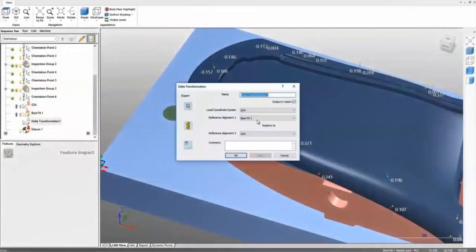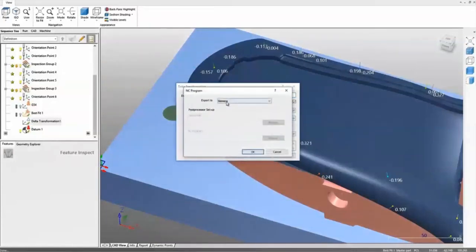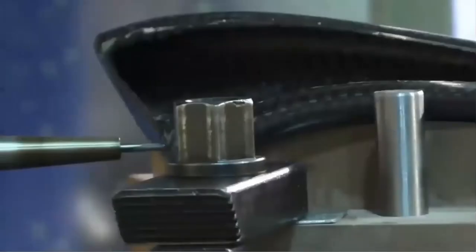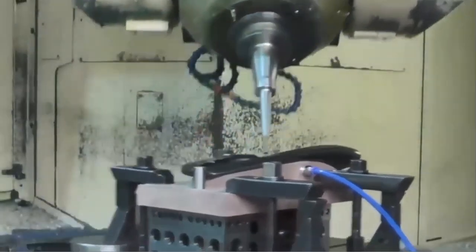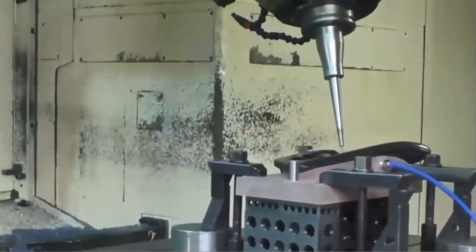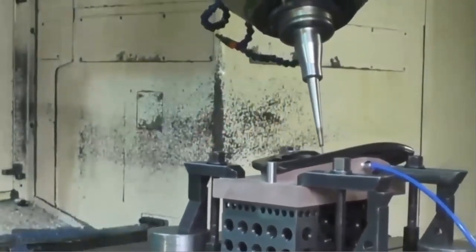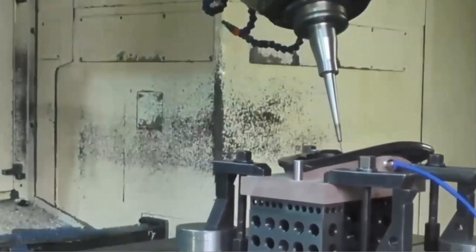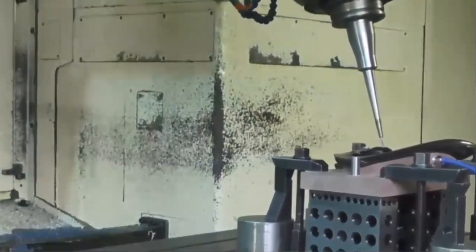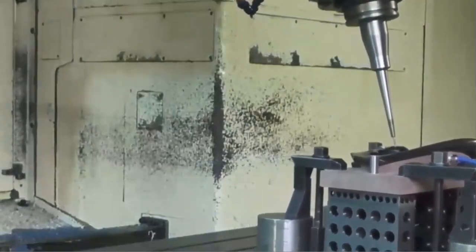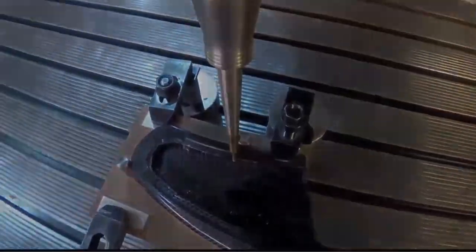Once the optimum setup has been determined, we can transfer the setup data either directly to the machine tool and run the nominal machining toolpath NC code, or we can transfer the data to the CAM software so that the machining toolpath can be re-exported using the optimized setup. Using PowerInspect, we can quickly identify parts that will not conform and ensure the machining process does not take place.